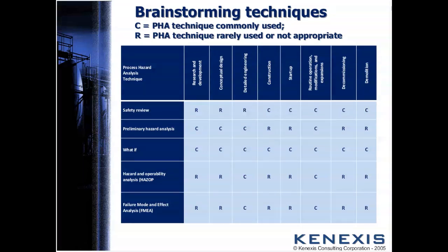The HAZOP technique was developed to evaluate and identify safety hazards in a process plant and to identify operational problems which, although not necessarily hazardous, could compromise the plant's ability to achieve design productivity. Most HAZOPs I do, people will find a lot of recommendations to improve quality and yield and operational capabilities, and reduce downtime. May not be a safety issue, but a lot of times HAZOPs are money makers.